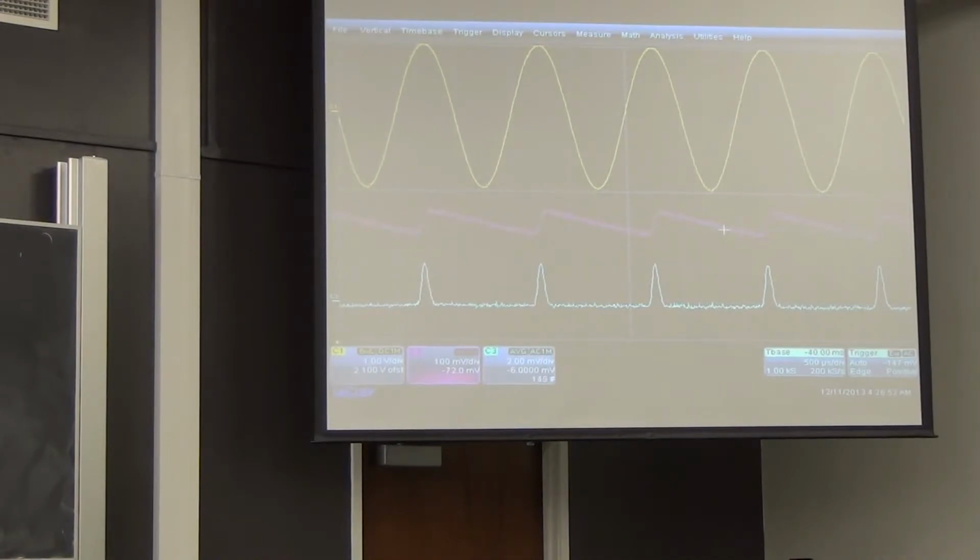So we've gone from 500 ohms to a kilo ohm, 10 kilo ohms. Last one in this is 50 kilo ohms. So we should see next to no ripple, which is the change in the magenta line, and very, very small current.